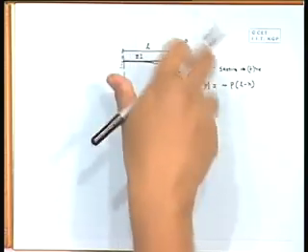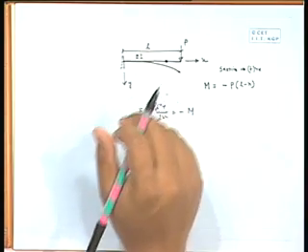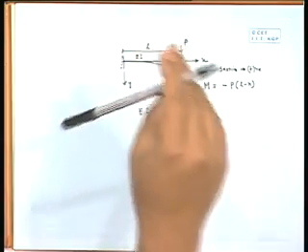The moment will be in that direction, right. So, that moment will generate tensile stress at the top. So, it is something like this. So, hogging moment, tensile stress will develop at the top. So, if we take sagging as positive, the moment we are getting is basically a negative moment. So, it is not sagging, it is hogging, and the value will be P L minus x.